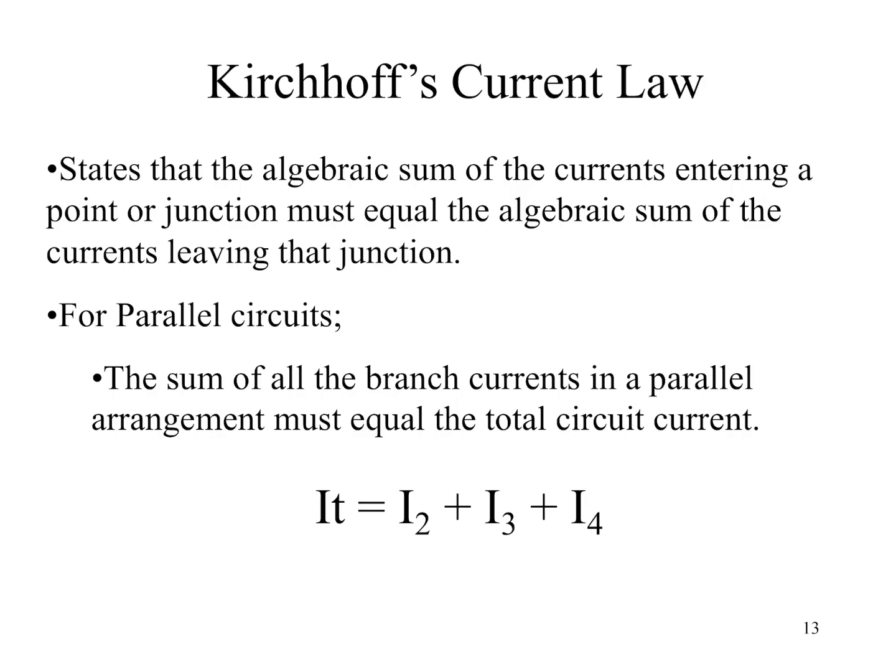So that's just like we said for voltages in a series circuit. When we take the voltage rises and add them to the voltage drops, the total sum is 0. When we take the total current in parallel and add it to the currents, we have a sum of 0. The current entering plus the current exiting equals 0.